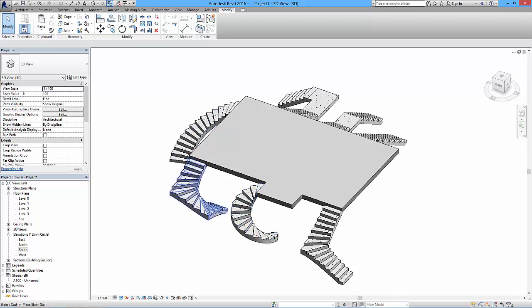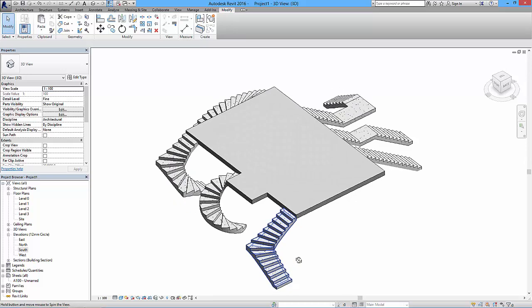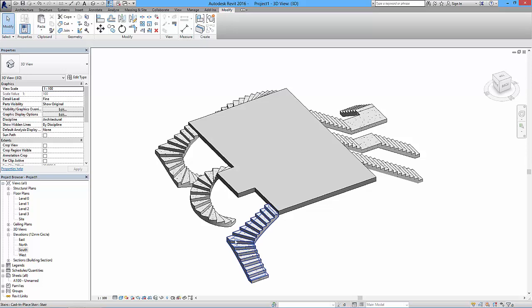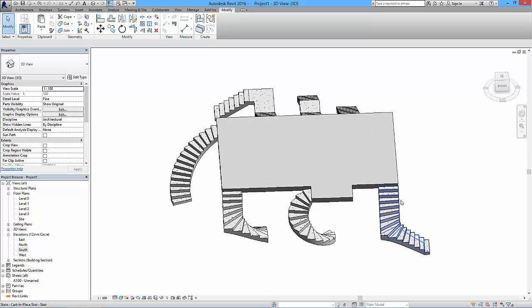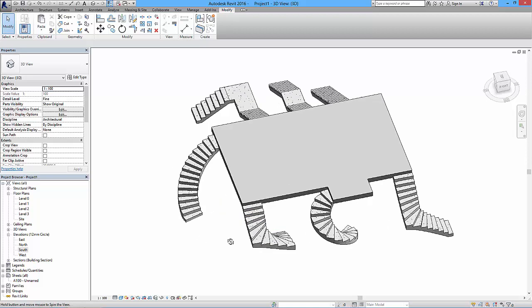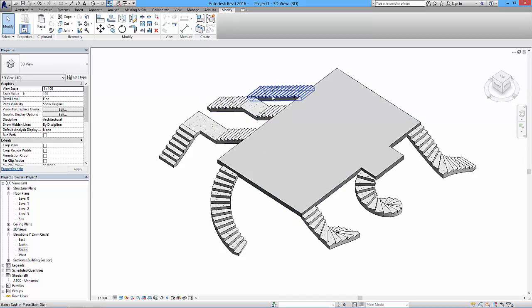This is a sort of U-shaped winder, and this is a dogleg winder. And these winders have these stairs that come in at various angles. Okay, so not necessarily the best way to create a stair, but if you're tight for space, then these sorts of things do come in quite useful. Another thing to just bear in mind is that there's no railings on these. We'll look at railings a little bit later, and I'll create these from scratch again and show you all the different options that we've got.